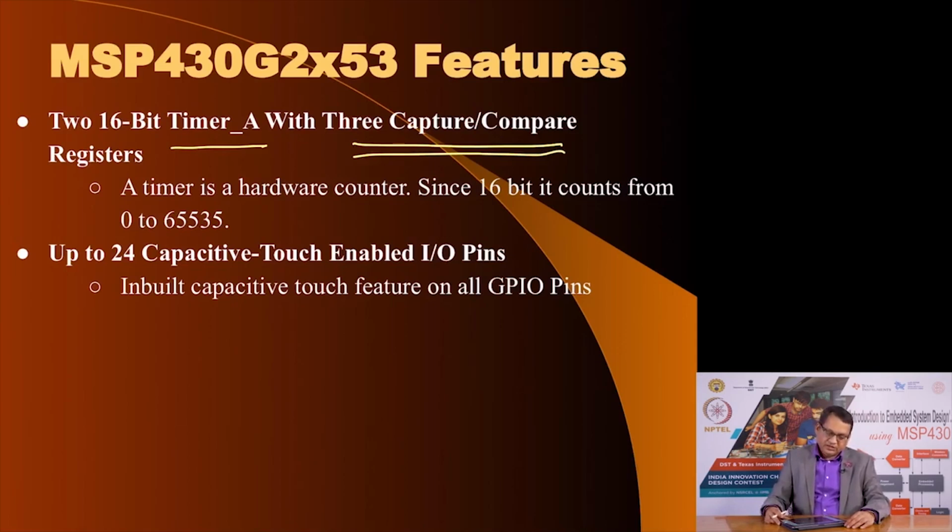The counter, these timers are 16 bit, and therefore, they can count from 0 to 65,535. That is the dynamic range of these timers and counters. It also has up to 24 pins which have capacitive touch enabled capabilities, and all the GPIO pins could be utilized for that. This is a very important feature of MSP430 microcontrollers.